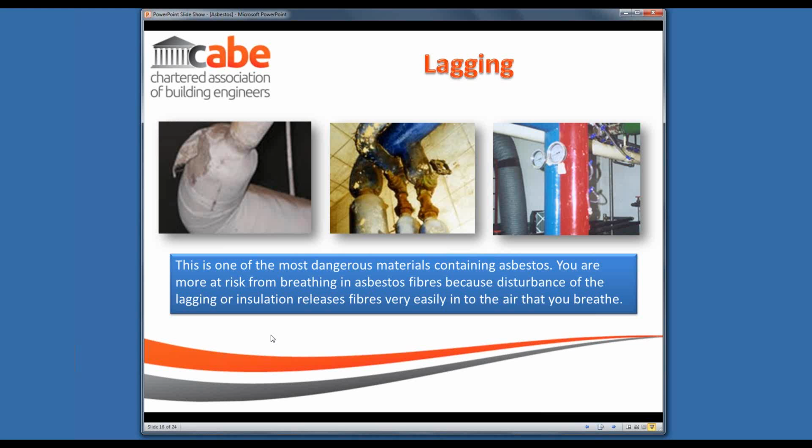These are clearly elements that would have to be identified in a risk register, asbestos register for a premises, for those in control of a premise, and the normal situation here would be to either look at totally encapsulating the material, or more frequently to get a specialist contractor in to deal with the removal.